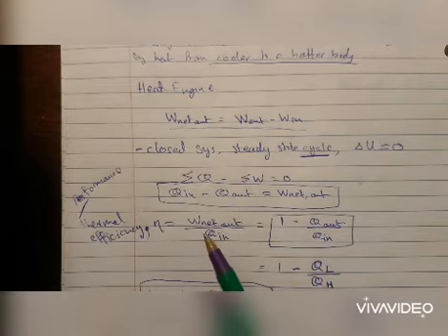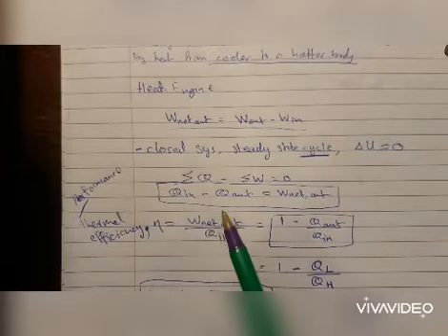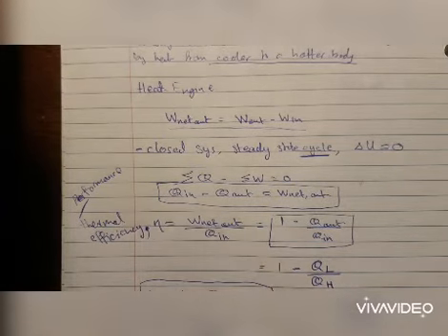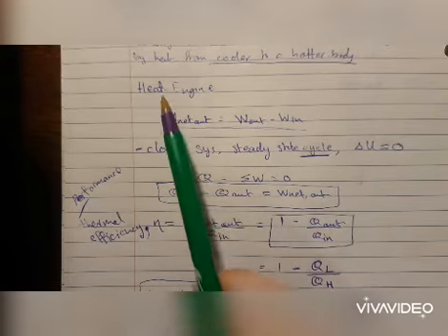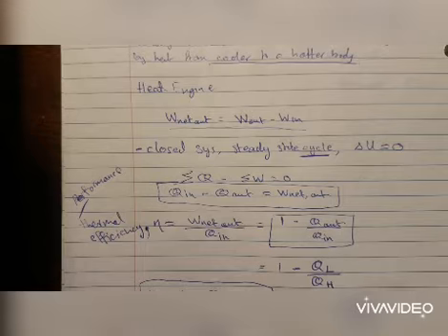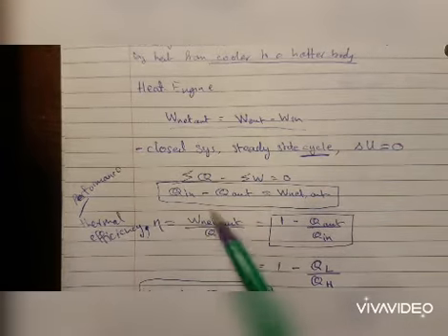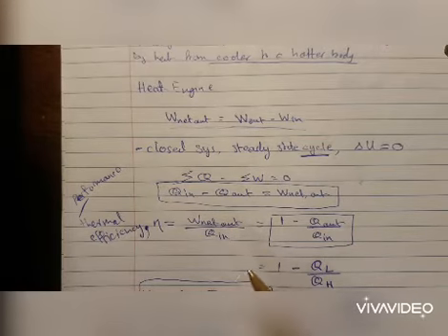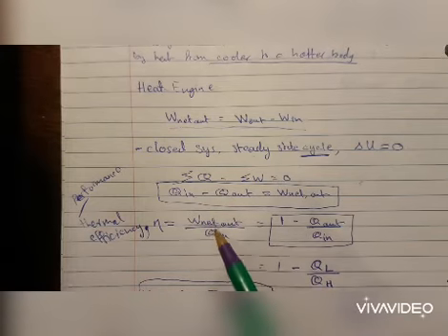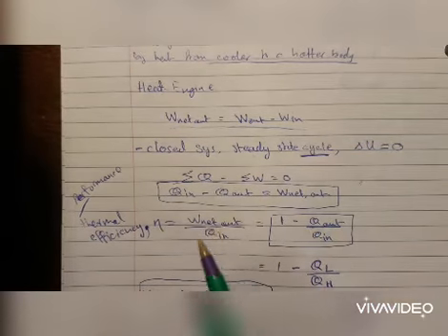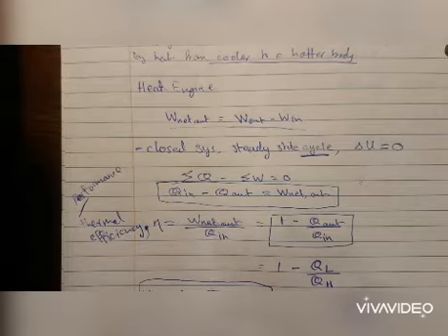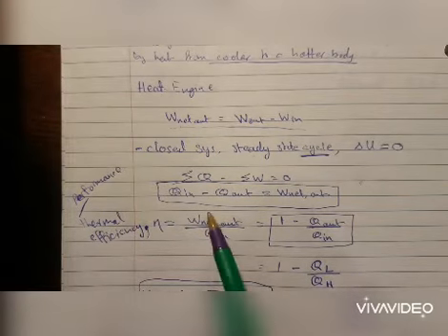So performance is basically measured by the desired outcome, like what are we looking for in our system to do. In our case, in a heat engine, for example, take the car engine, we're looking for it to do some work. So the work net is what we really need, but what's the driving force? What do we require to make that happen? We need heat. It's a heat engine. So Q in is our required cost to produce the work.